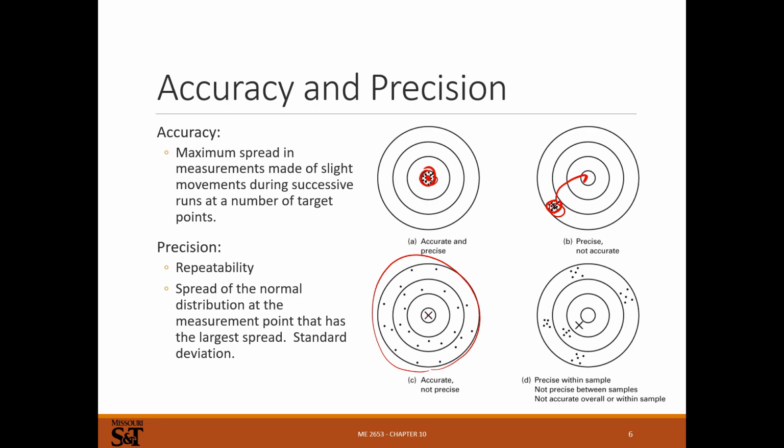In the BB gun example, the tolerance of the BBs themselves, the tolerance of the bore of the BB gun, the air pressure tolerance, the ability to hold the thing stable while firing, all those things matter, and those are the hard things to fix. Adjusting the sight's the easy thing to fix. So usually precision is the key, and then accuracy you can fix.